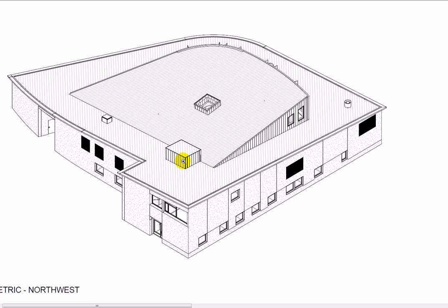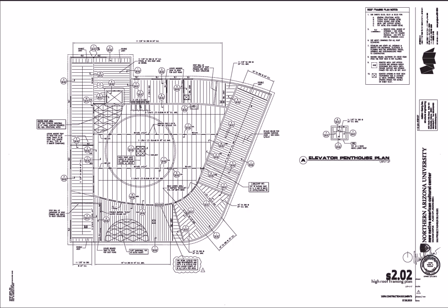And so by looking at that, I can see, okay, we've got all these different framing systems going on. So you can see this is an elevator shaft. Here's a little skylight. This is one roof sloping like this. And then we have this perimeter roof going around. So really there's a lot going on here. What I thought was useful by doing this little exercise is just to walk you through my thought process as a structural engineer when I go through a set of drawings, the things I look for and the things I go through.